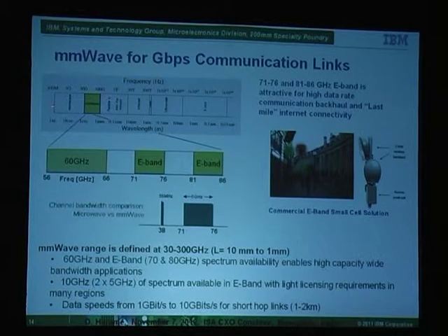So this is the spectrum. You can see that the previous methodology really had a fairly low data rate. But when we start going up into the bands like 70 and 80 gigahertz, these E-band, instead of like 56 megahertz, now you got a 5 gigahertz band. So this is just transforming. So if you look outside, you see these towers, start seeing these round things on, as well as these rectangular ones. And those are all this wireless backhaul. So this thing has just completely transitioned it.